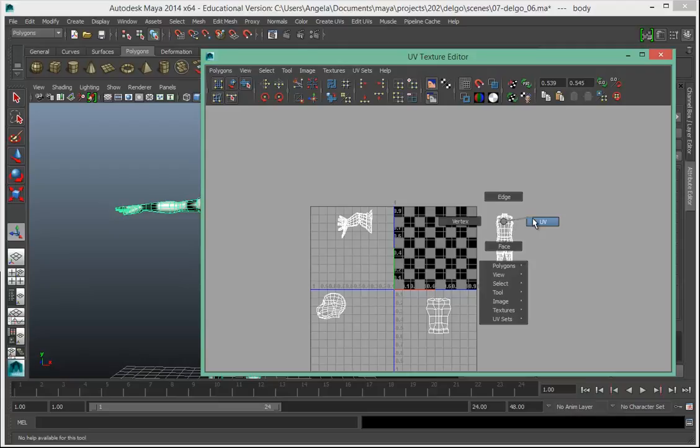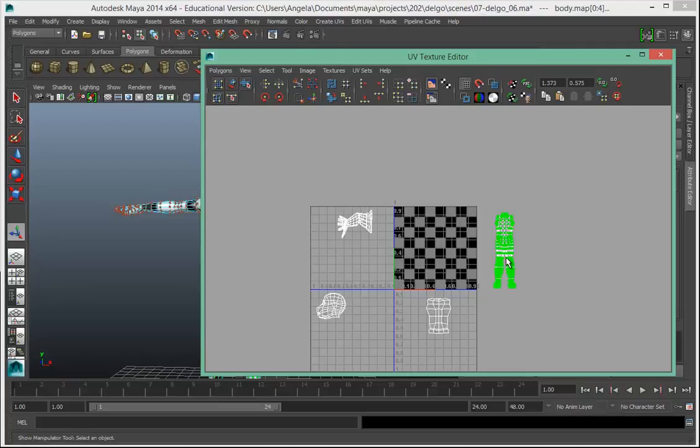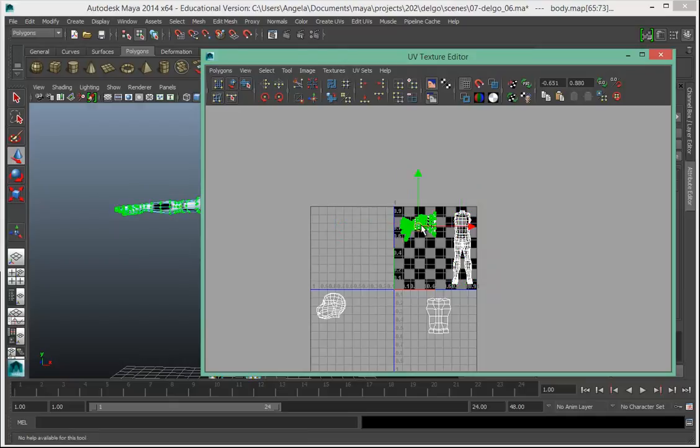So I'm going to right click and go into UV mode and select as much as I can of the character and move them back in. Select the arms, move them back in. If by chance you don't select the whole thing, for example, and you go like this, stop what you're doing, press the Z key, unselect, and select the whole thing. If by chance you made a mistake and you dropped one on top of the other, it is virtually impossible to select one and not select part of the other, of course.